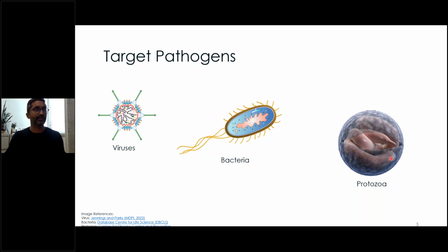And so sometimes having a combination of both is quite good. So that you can maybe do primary disinfection with UV and then have chlorine and a residual in your distribution system. It tends to be a good combination. But if you don't, you can still treat protozoa with chlorine. That's totally fine. You just need to be conscious of how much CT you need in order to do that. And what do I mean by how much CT? That's the point of this webinar, so we'll talk about that.